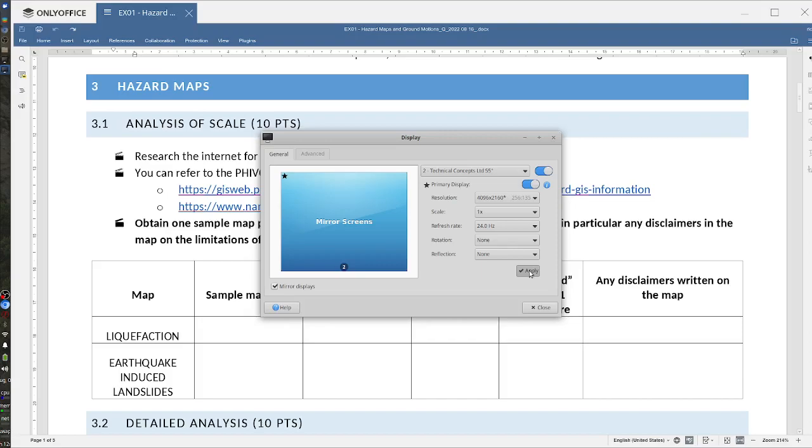So I have this map here showing Mapua Intramuros. That's the exact location of the Aupang building. And this is what Google Earth will look like once you open the PHIVOLCS map. You can easily see the nearest faults here. So you have your Valley Fault System, and then you have some faults from Zambales, from Quezon. So you can just choose the three nearest ones and list them down.